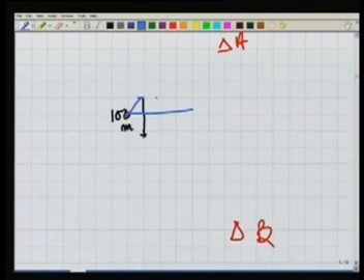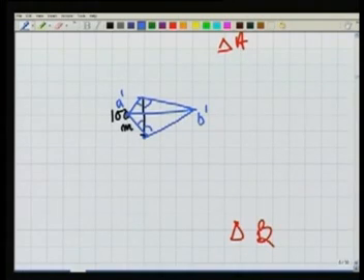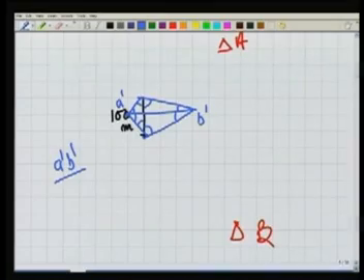Let us say I establish just 2 points here, point A dash and point B dash. Then I measure these angles. All these angles are being measured by theodolite. Theodolite can measure the angles, that's not a problem. Once I have measured all these internal angles, I know the length of this black line. We had measured that, it was possible for us. I can compute the length of line A dash B dash. So the length of the line A dash B dash is computed.